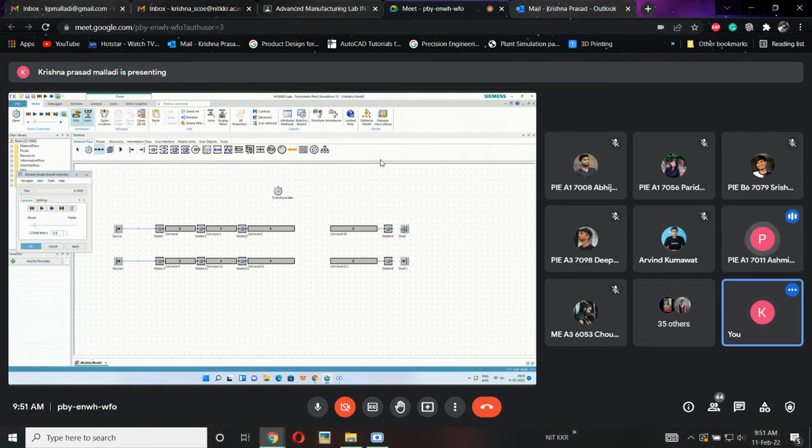Sir, when you copy and paste, the names of these stations or conveyors have numbers. Is there any pattern in these numbers? Yes. See, this is the reference. Conveyor 2 1 is the initial number. Now, if I copy and paste, what will happen? 2 will be the parent, and the next number will be the subordinate number. That is why 2 1. If I copy paste this one, the main name is the parent name, Conveyor 2.